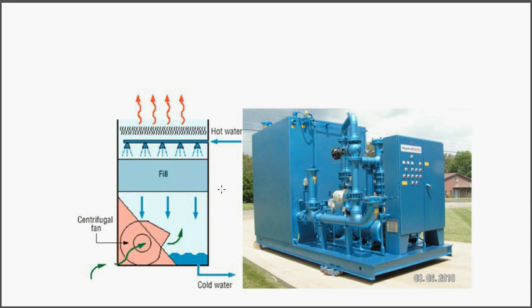In this system, you can see this machine, it uses evaporative cooling, where water evaporates, and you've got a centrifugal fan to blow the air, and as a result, you get cold water leaving the plant. So it doesn't cool as far as freezing water, but it can cool it quite a few degrees. So it's a system which is used.